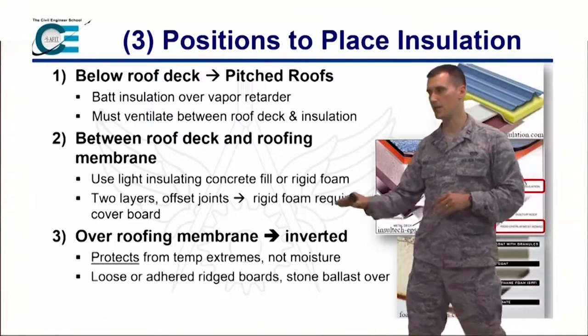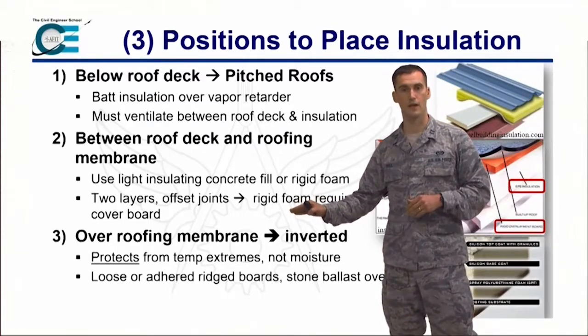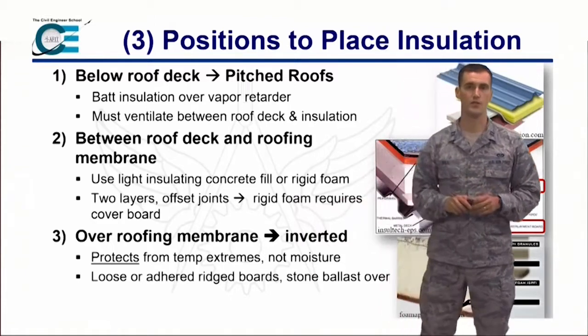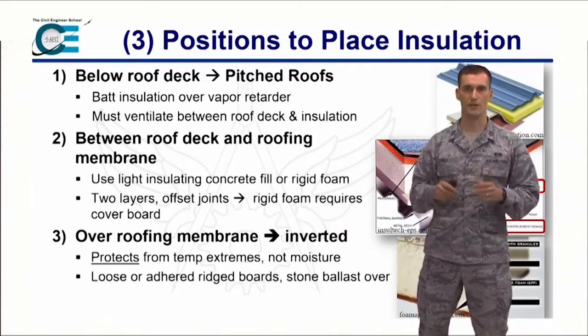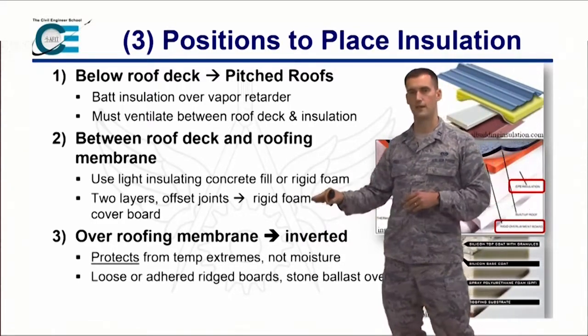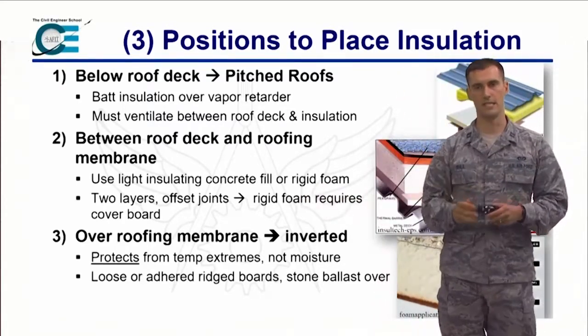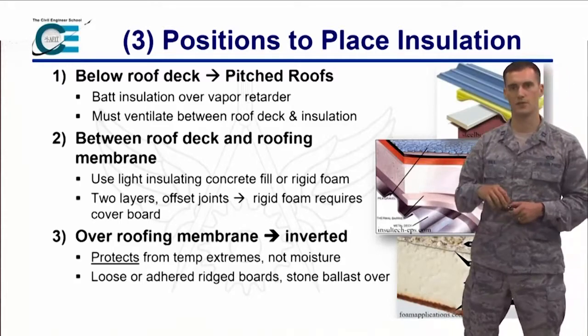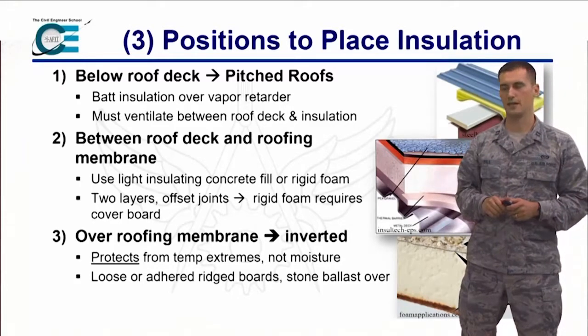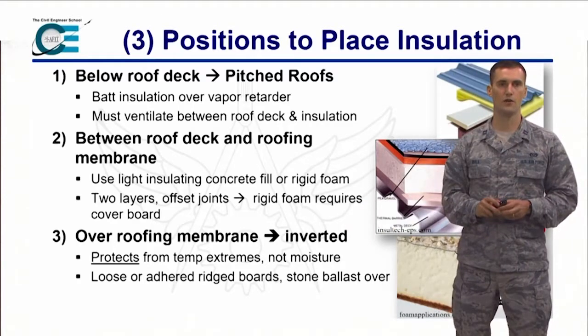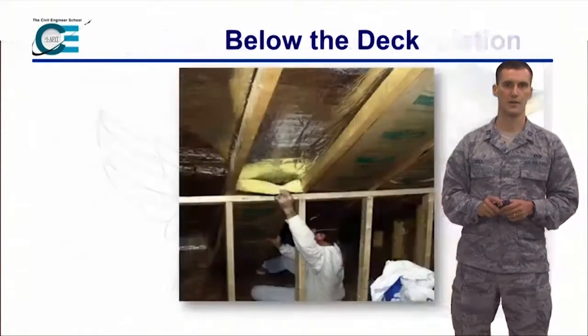The key here is you're going to need a very specific insulation that can withstand the moisture that it's going to be exposed to, the elements, that sort of thing. Otherwise, as insulation predominantly gets wet, you're going to have derated capacity, derated value, and so that's something to consider as well. So typically we're going to use XPS insulation in an inverted roof, which we'll talk about here.